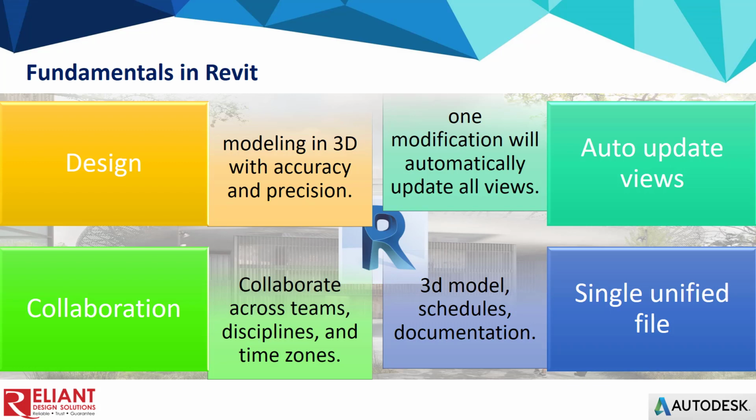The elements have their own properties or parameters that work intelligently and could ease our modeling work inside Revit. Then the model can be further visualized and analyzed. Compared with AutoCAD, inside an AutoCAD drawing file, usually your drawing consists of lines, geometries, and blocks. This is because AutoCAD software is mainly for drafting 2D and 3D drawings. So Revit is for designing 3D models, while AutoCAD is for drafting 2D and 3D drawings. So that is fundamental of Revit number one.